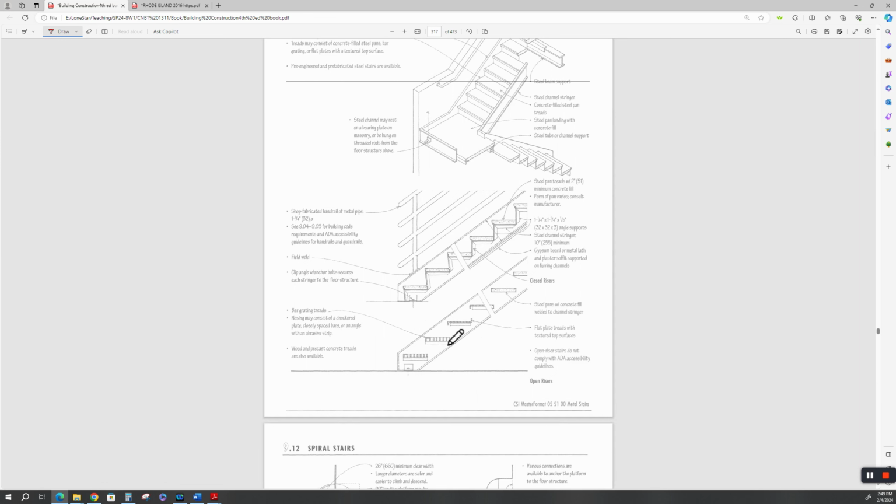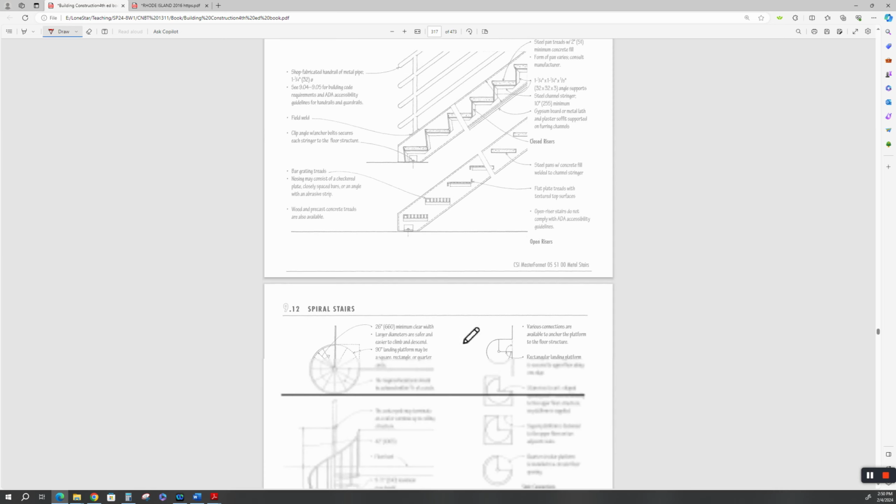This is what I call a real steel stair. So you've got your stringers that are structural steel, and then you've got flat plate treads that have some sort of textured surfaces on them of all manner. Sometimes it can be bar grating, like in an industrial plant. A lot of wastewater treatment plants I did, that's how we did the steel stairs. We used structural bar grating between the stringers. It's very slip resistant, very durable, and it worked really well.